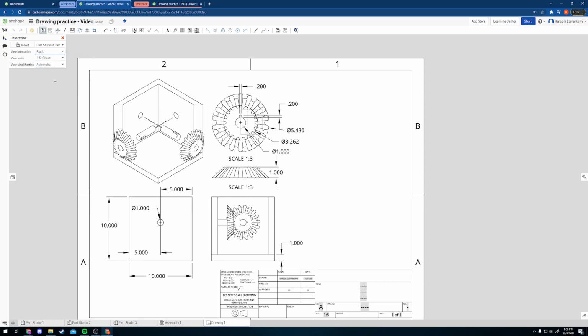And you can see this is way too small. We have plenty of room on our sheet, so I'm going to go ahead and change the scale to 1 to 2. Plop it down here somewhere on the right. The exact layout of this drawing isn't super important, and you can really do it however you'd like as long as you convey the correct information.